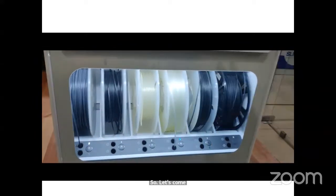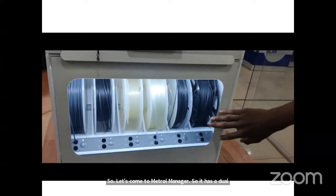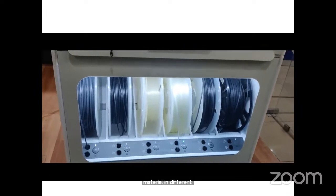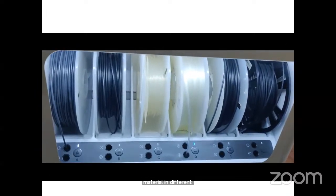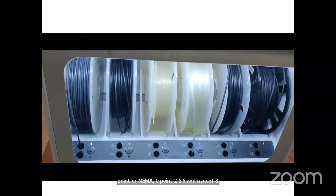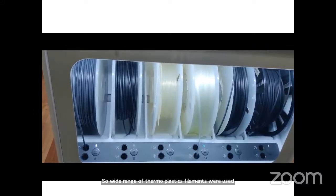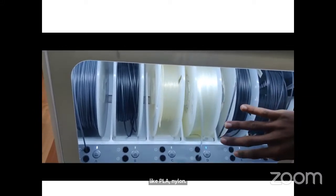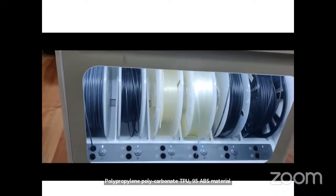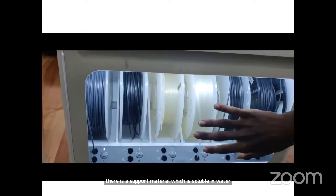So it has a dual extrusion technology, for build and support material in different nozzle diameters like 0.4 mm, 0.25, 0.6 and 0.8 mm. So a wide range of thermoplastic filaments can be used like PLA, nylon, polypropylene, polycarbonate, TPU 95A, ABS material, and there is a support material which is soluble in water, that is PVA natural. We are also using that.